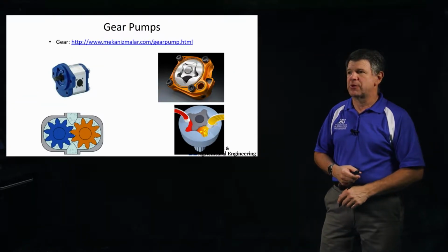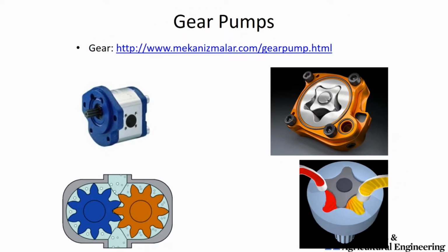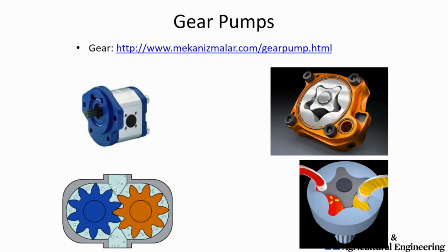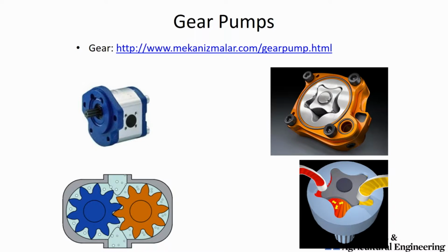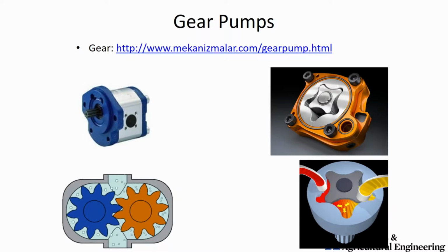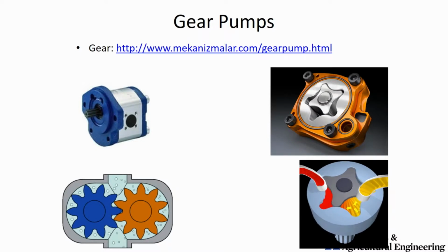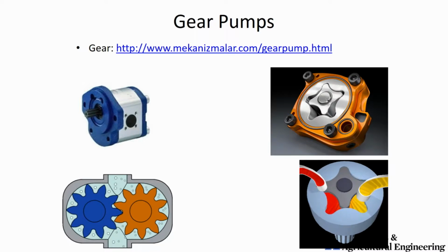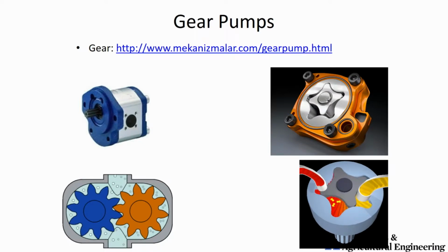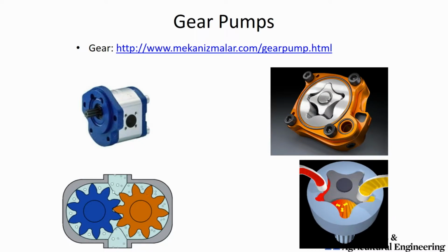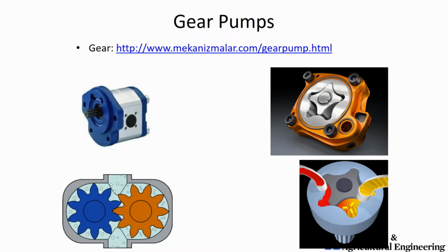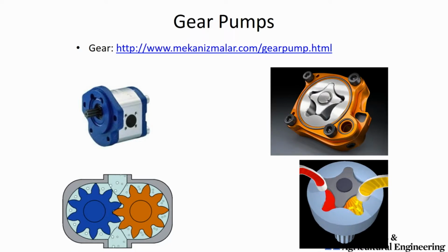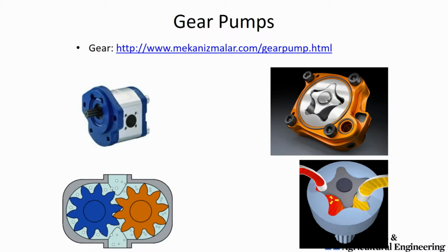So the gear pumps are some of the simplest, and in fact the cheapest pump you can buy is that external gear pump that you see on the left there. And you can see how the material flows through that. There's two gears that run together. They mesh in the middle tightly, and a lot of times we think, okay, it's grabbing the material and pulling the material between the gears and pulling them down as we're looking at that drawing, but that's not true.